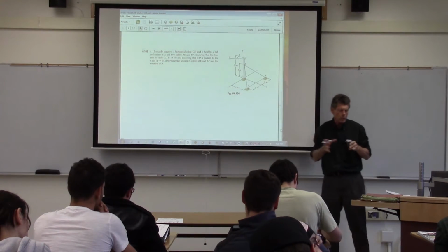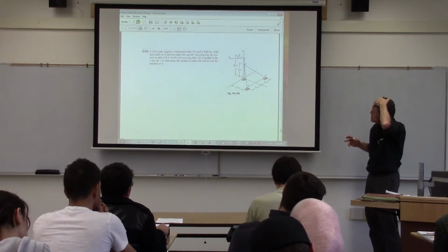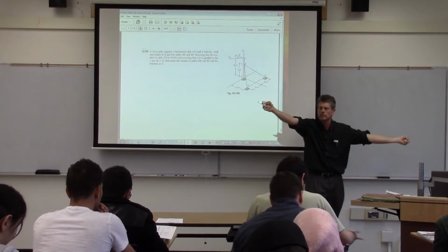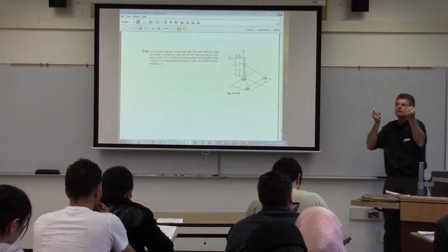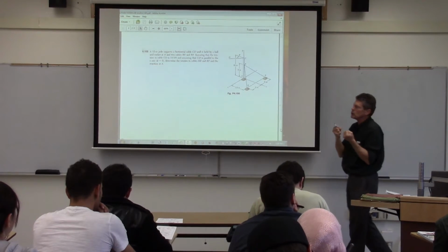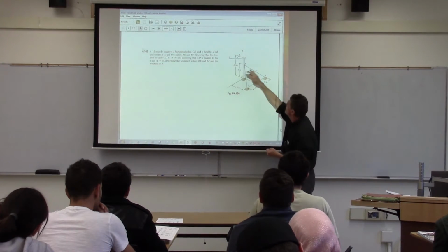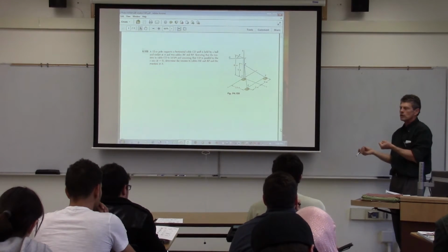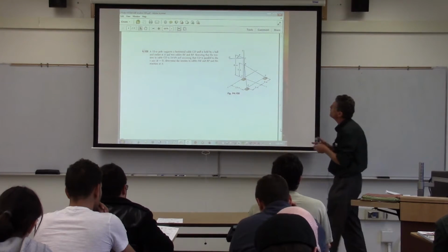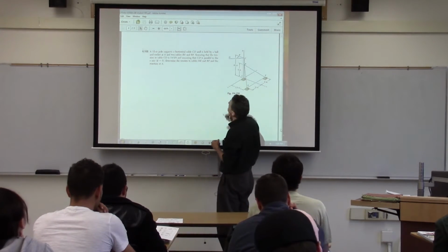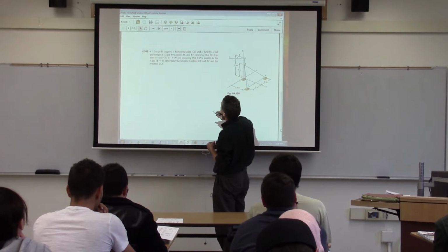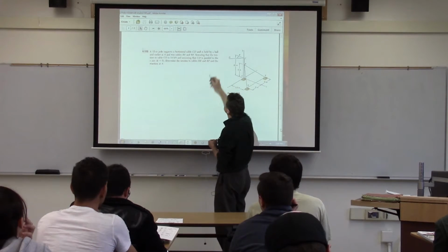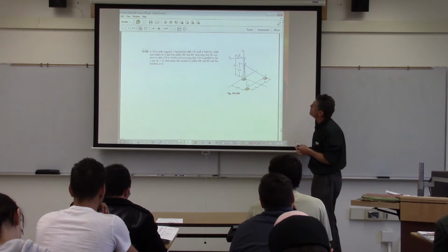Okay, so we've got the situation that we're pretty familiar with now, especially with 3D forces. We've got a bunch of cables that we've been given the endpoints. So we're going to end up doing a lot of unit vectors, because we're going to have to get those force vectors from BE and BF into some sort of a unit force. Then it'll be an Fx component that we'll solve for, an Fy component, and an Fz component. We've got cable D that I think has load on it. Tension in the cable is 14 kilonewtons.